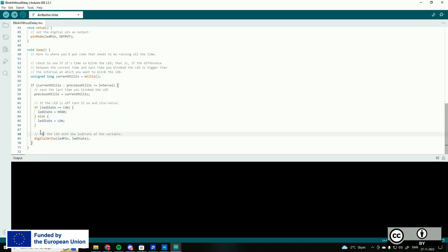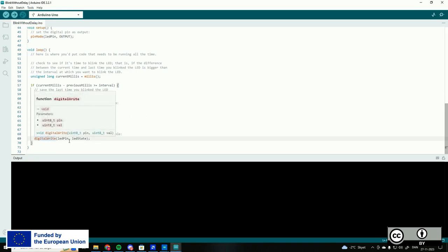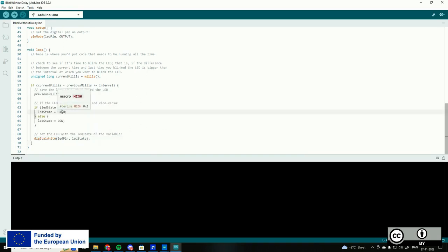So digital write. The other option is digital read, which is one of the most basic functions in Arduino. Again, remember the analog and digital signals. Digital meaning we deal with ones or zeros of 5 volts. With digital write, an LED state of high means 5 volts, or low, which means nothing, to the LED.